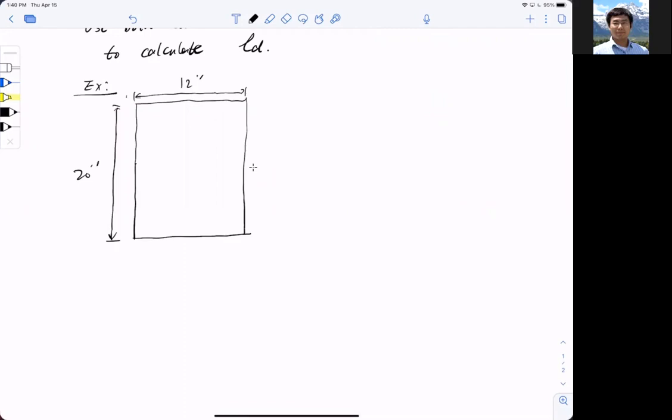So I have bars here. Let me use blue color. One, two, three: three bars, let's just say three number 8. And then I also have stirrups, a hoop going through them, for shear and for confinement. I'll tell you straight up that when I pour this concrete, it's an upside-down pour, and I have more than 12 inches of concrete buried underneath the bars.